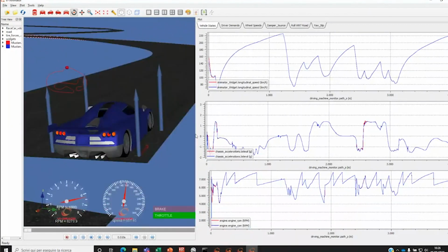In this context, of course, it may happen that for specific tracks where we have not laser scan information, we do not have full detail of the road surface, and so we need maybe some additional insight about how we can tune the vehicle model in terms, for example, of damper settings, in a way that also the road irregularities are being considered in a proper way.